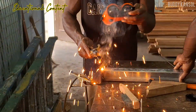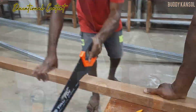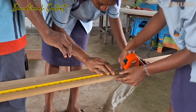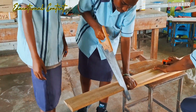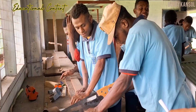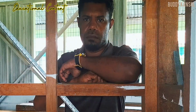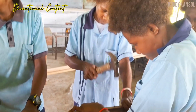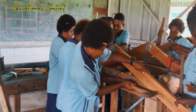The process began with the cutting and fabrication of 50 by 50 mm square hollow section galvanized steel pipes, which were used for the structural posts and bracing. This was followed by the precise measuring, marking, and cutting of 50 by 70 mm hardwood timber to create the primary frame members. This stage involved assembling the frames, then cutting and fixing weatherboards to the walls, and finally cutting and nailing tongue and groove boards to the floor.